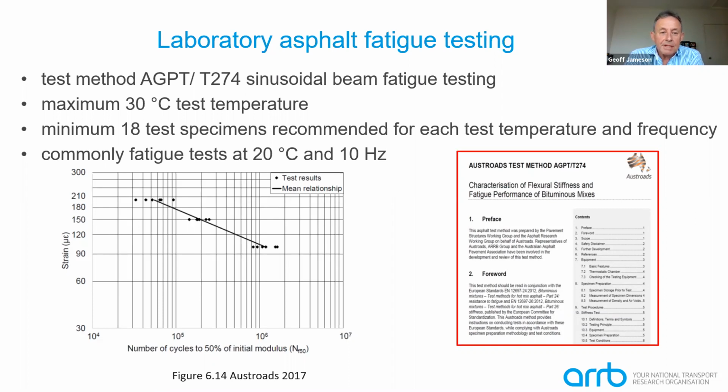Now, one of the limitations again with this is that the maximum temperature that you can use for this test is 30 degrees. And there are situations like in Brisbane, as we saw earlier, where we'd use a weighted mean average pavement temperature of 32, where we can't actually do a laboratory fatigue test at that temperature. So that is again a major limitation of the methods that we have available to us.